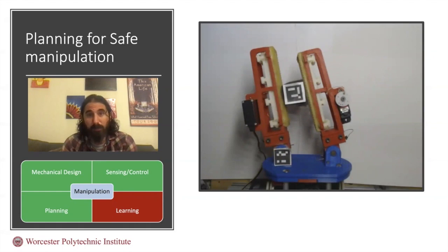However, we do need to change and fine-tune the force that we apply to the deformable object based on its stiffness. So this would require an initial exploration stage with the hand, perhaps squeezing the object and checking the actuator force profiles and understanding what kind of force we should apply to a given object.